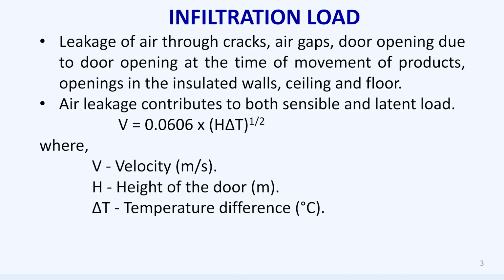Let us see the next heat load, infiltration load. As I had explained in the previous lecture, infiltration is nothing but the leakage of air through air cracks, air gaps, and door openings. The door opening, especially at the time of the product being loaded into the cold room, and also during the movement of the products.